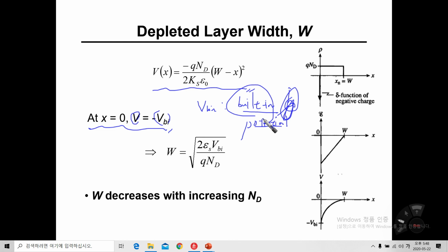However, the ionized dopant atoms are left behind, tightly bound by the silicon atoms. This is the main mechanism of how the electric field in the depletion layer is formed internally. So we can call it the built-in electric field.